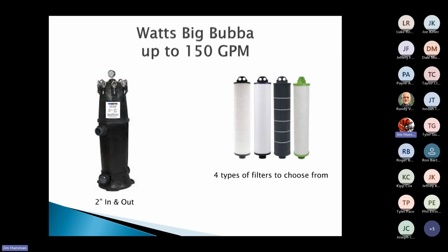But just remember, each filter does something a little bit different. If we're trying to get debris, jump into that pleated. If we're trying to go after taste, go after that carbon. But don't just throw carbon in just to catch it all. You're just throwing a filter in the garbage really, really quick when it does not need to be.